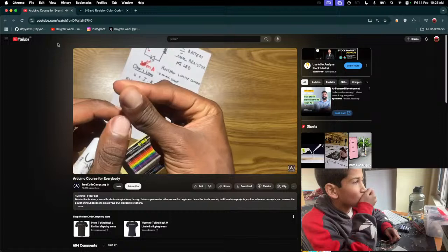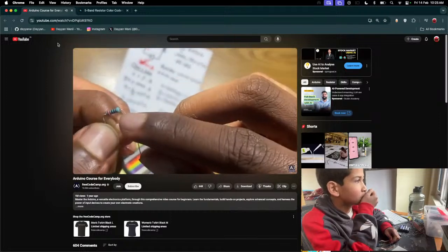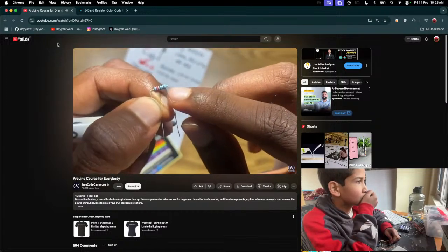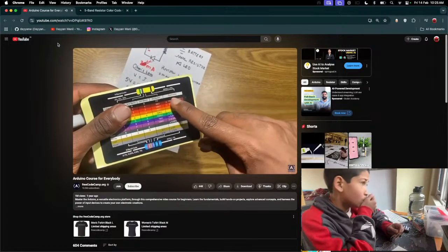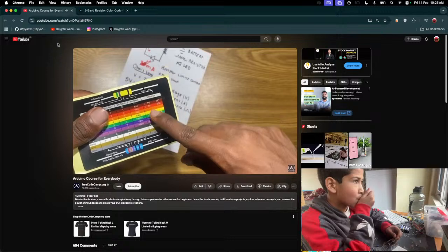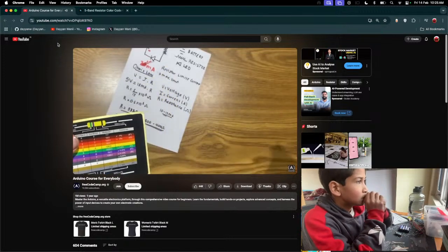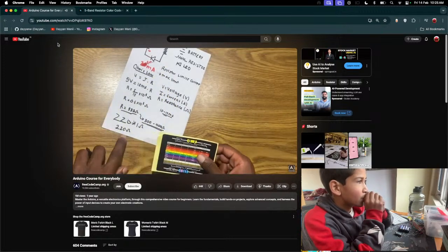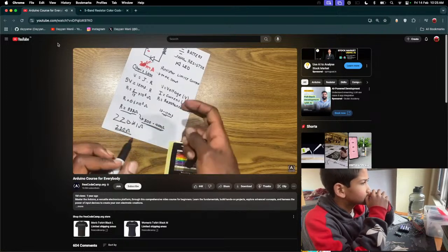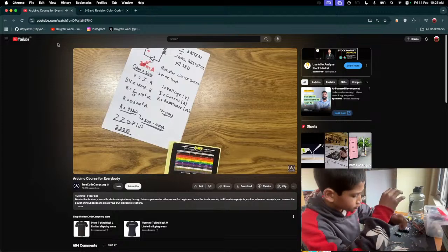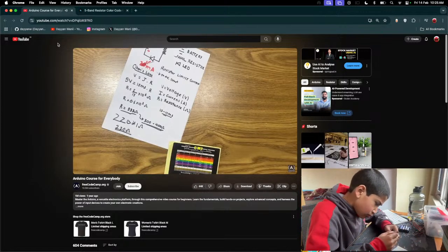If you look close enough, there's a fifth band right here that looks brown. This is just tolerance, and we're not going to get into it because it's not really important at this level. Okay, with that in mind, we have 220 ohms of resistance. So you can check your resistor by looking at the color codes. Okay, there's also another way to actually do this.